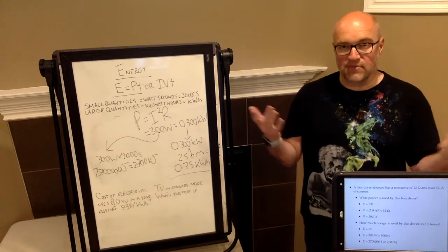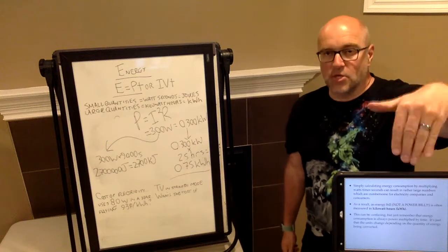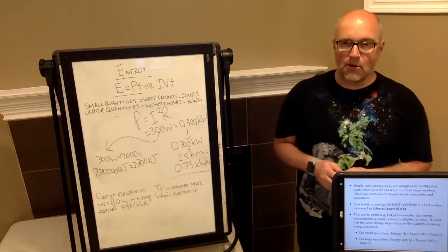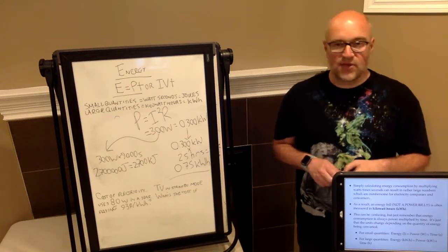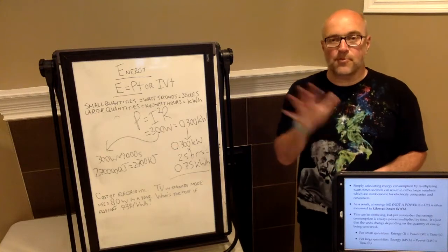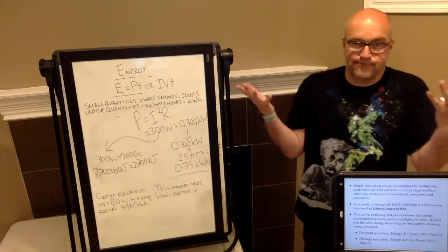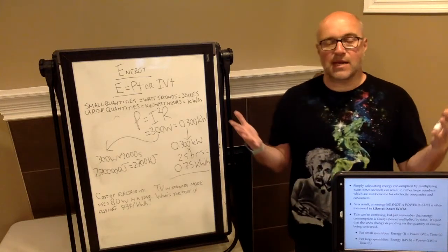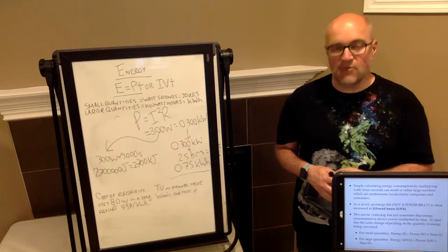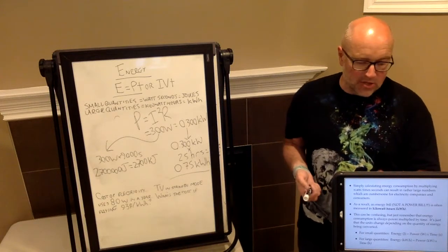So there you go, a couple of different answers depending on what you're going to do. And again, a reminder: two different units for energy, joules for small amounts of energy and kilowatt hours for larger amounts. Joules, at the bottom of the slide here, are very important. Joules are watt seconds, whereas kilowatt hours are kilowatts times hours, so you can't really get kilowatt hours wrong because it tells you the power and time units. You just have to remember the joules are watt seconds. If you remember that, the calculations are pretty straightforward.